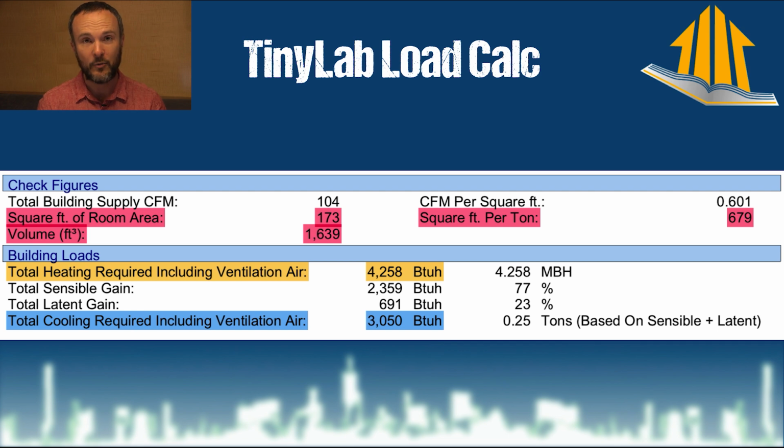What I have done at that point is intentionally and very dumbly detune my enclosure from my engines, because I don't want just my enclosure to be tuned and my engines to be tuned. I want them to be tuned to each other. So I want my air conditioning system, which I can only buy at the smallest, 6,000 BTUs per hour, a half ton, which is what I've got here. That's double oversized already, but I can't install less than the 2x4 insulation I've got in the walls because I would feel bad about that.